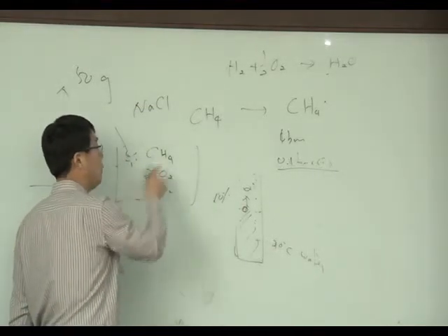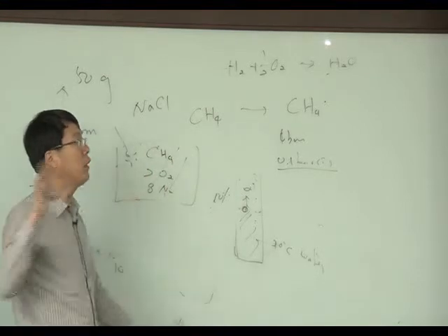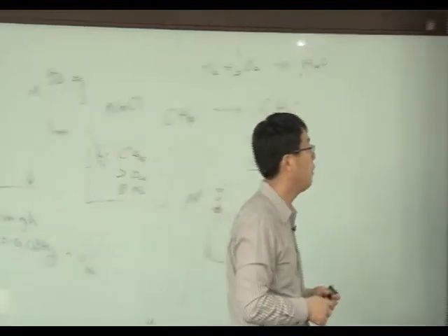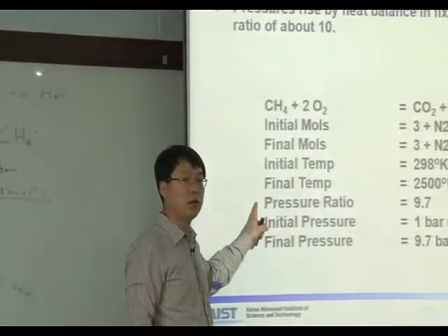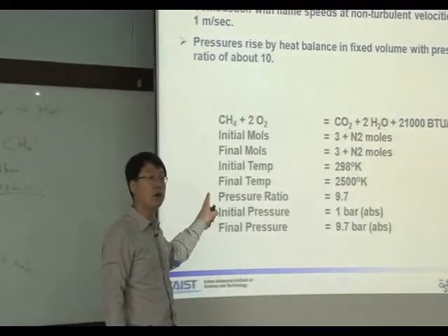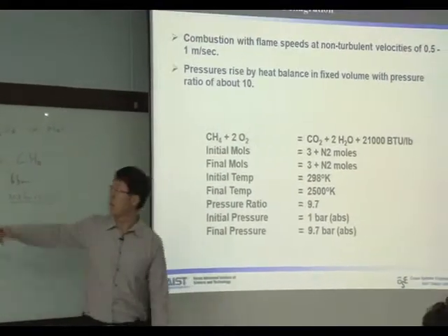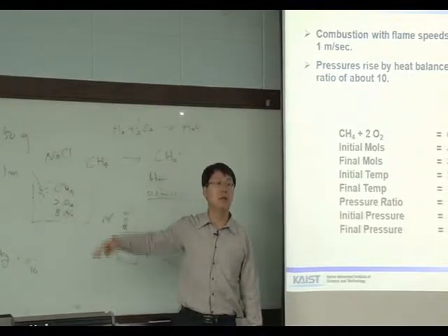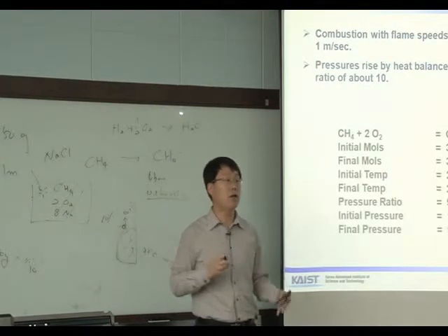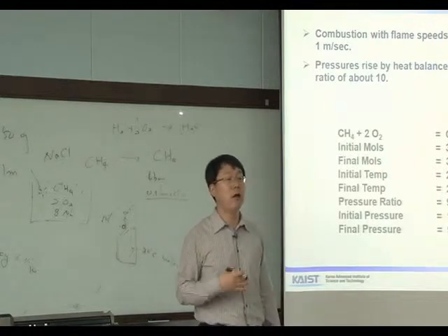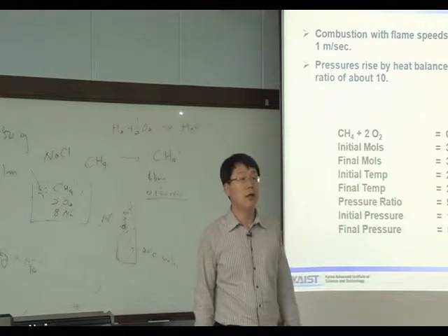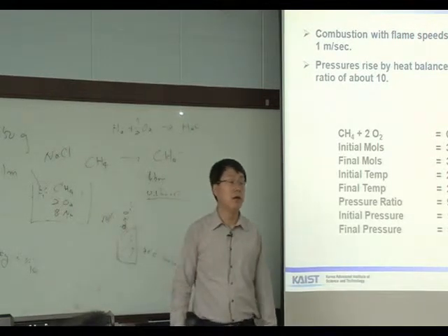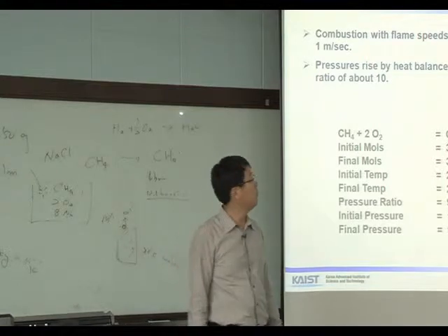But the energy here should be increased. The energy increase is reflected in the increase in pressure. The initial pressure 1 bar should increase to 10 bar if this system is closed. So what I mean is that the effect of pressure increase due to fire or explosion is caused by the thermal energy, not the increase in number of molecules.